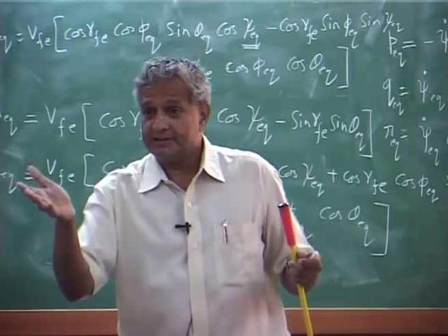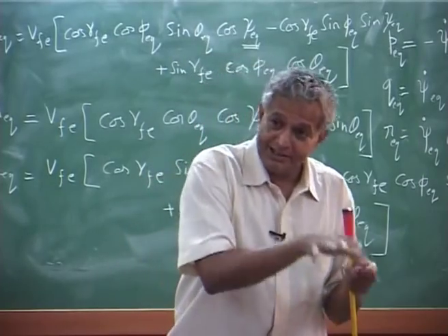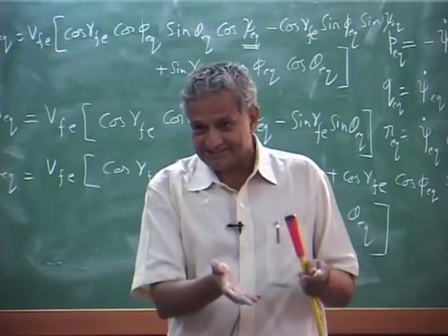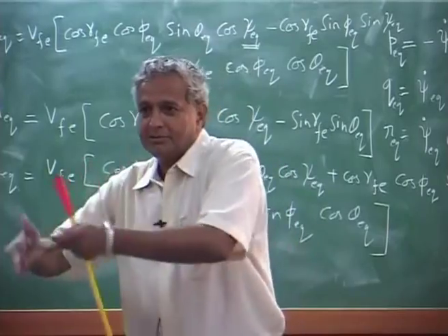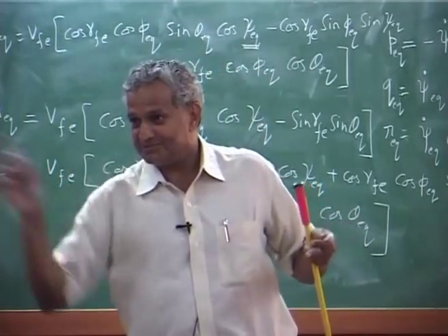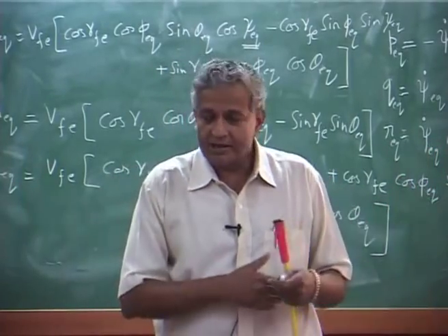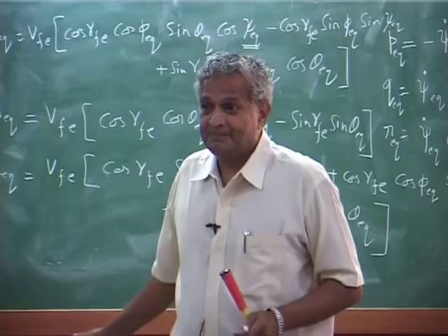But you go to forward flight at some other speed, then you will have an equilibrium and a perturbation for that. Like that you will have equilibrium, perturbation, equilibrium, perturbation. You cannot say this perturbation will lead to that perturbation. If you want to solve the full problem, you have to solve the complete nonlinear problem.